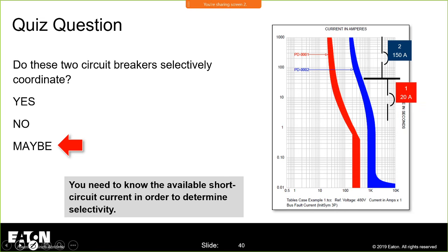So I'm going to take a look at some of the chat window here. I see some discussion going about three-phase or phase to ground. Selective coordination for all currents and all times. You must use three-phase fault current and ground fault. That is correct, Joe Pavia. You have to use both, and sometimes the ground fault current will be greater, depending upon where you're at in the power distribution system. They both have to coordinate.